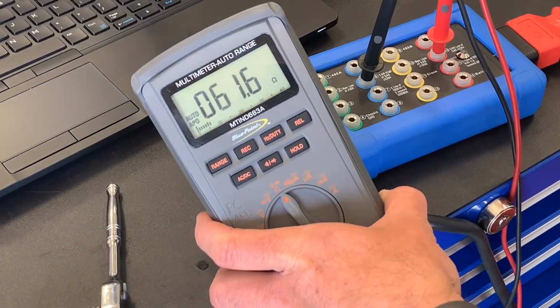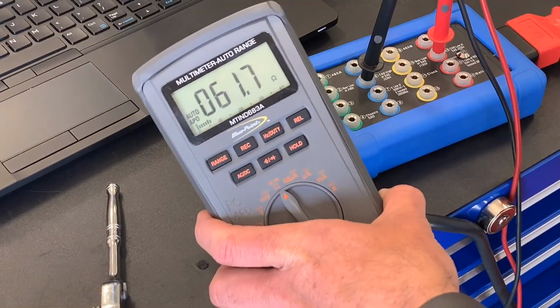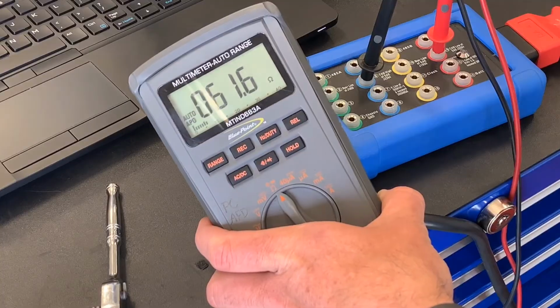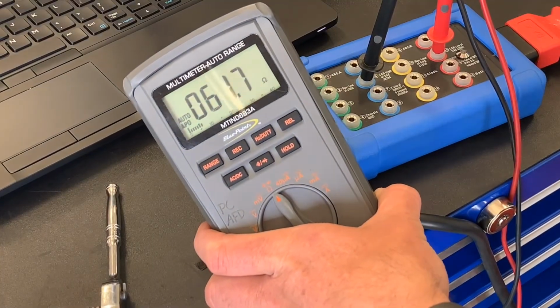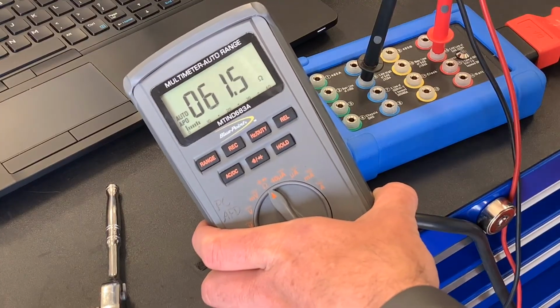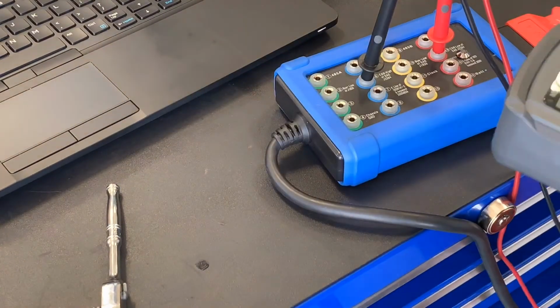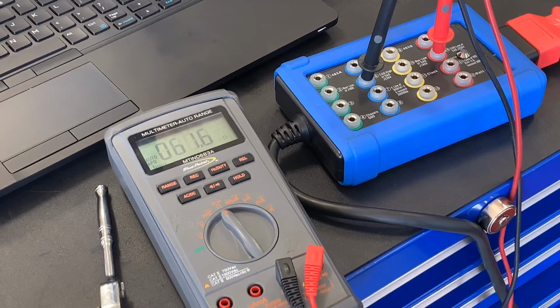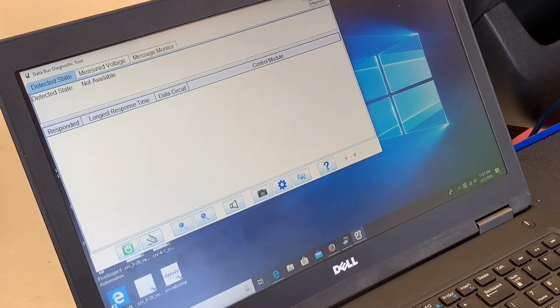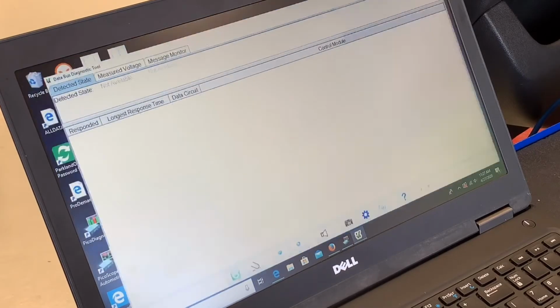This is a good short test to do if I had a network fault, just to confirm the viability of the operation. And then from that point forward, I would have to go on to individual modules and do checks from there. There's some really cool tools that exist for doing those checks. One of the cool tools that exists for doing these kind of checks on the General Motors side, so specific to this truck, General Motors developed this tool called the Data Bus Diagnostic tool.